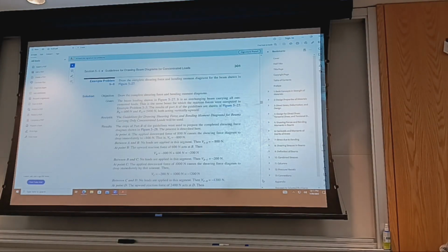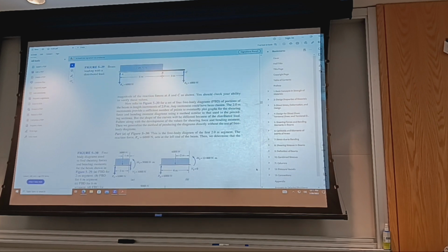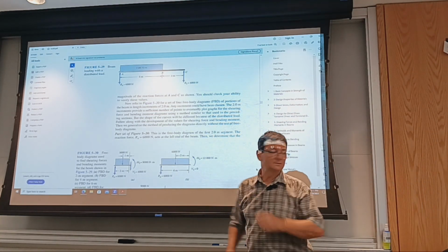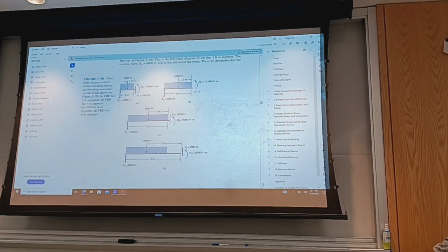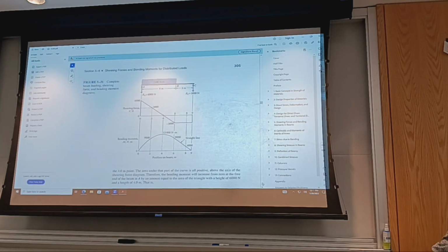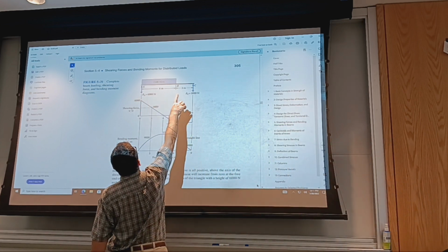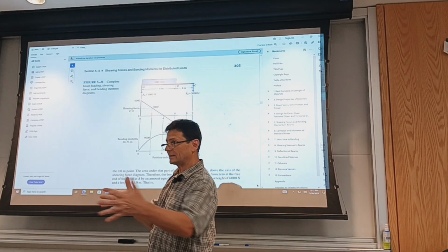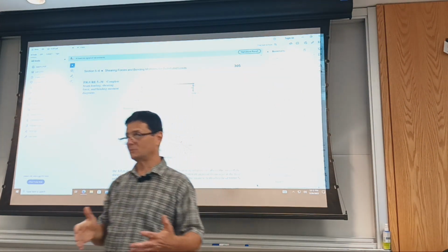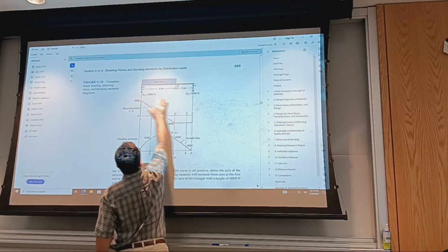We also learned that there can be distributed loads on diagrams. All right. So distributed loads cause the shear diagram to change degree. So if you have an evenly distributed load, on one hand, you need to calculate reactions, and this is something you've done in statics.